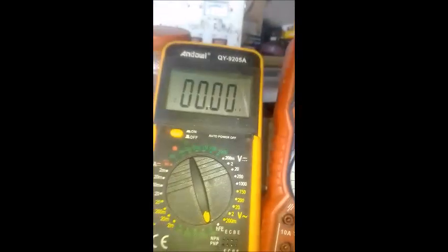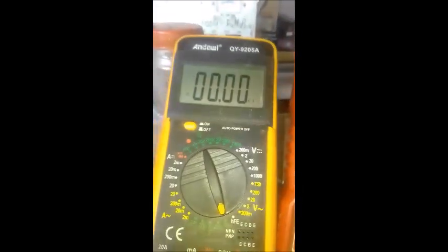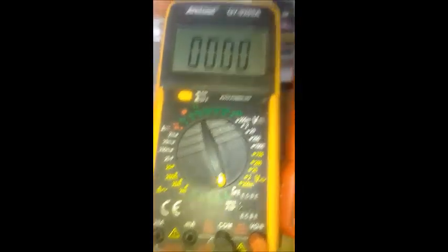Right, so how are we going to check? First we check the capacitance. I'm going to use this meter and also that meter. I have 2 meters to compare so that we can check the capacitance. This is how I got these capacitances of the MOSFETs. Measure together. First with this meter, I'll show you.